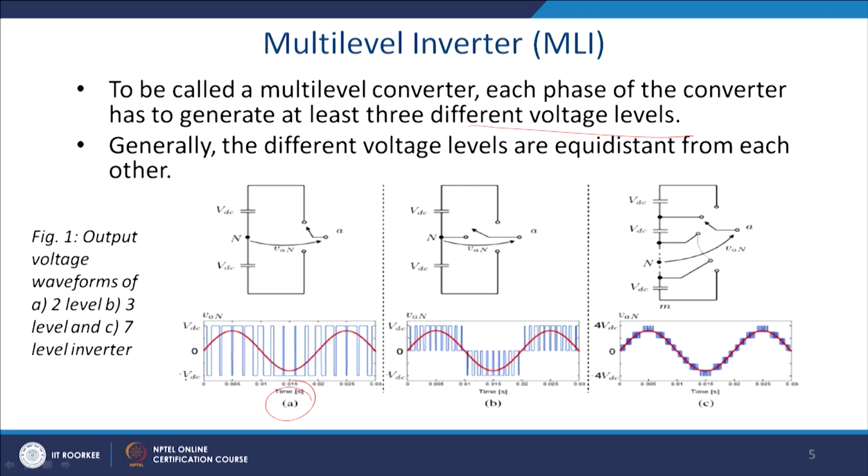We have discussed the unipolar PWM and bipolar PWM, this is the bipolar voltage. So, the voltage sticks to either plus VDC or minus VDC. In that case, there is a high dv/dt. For a half bridge it is VDC, for the full bridge it is 2 VDC. That is the instantaneous difference of the voltage, and the rate of change of voltage is also extremely high.